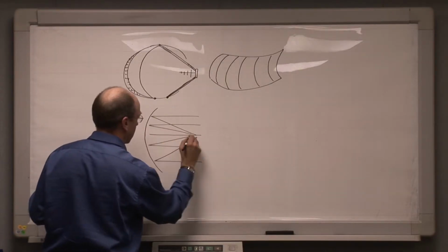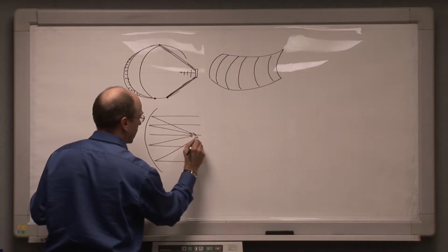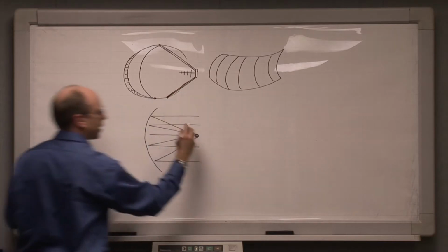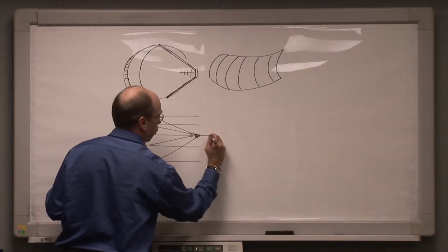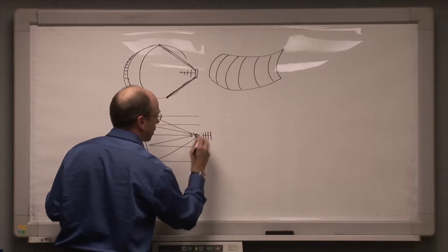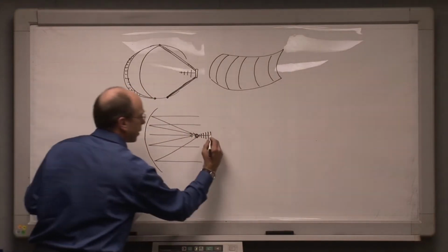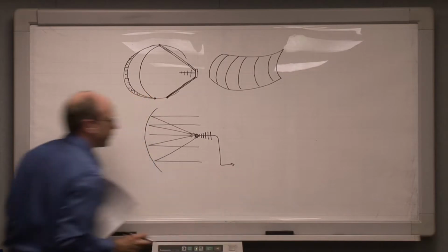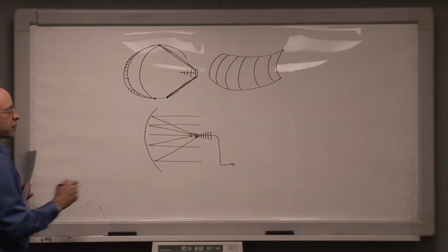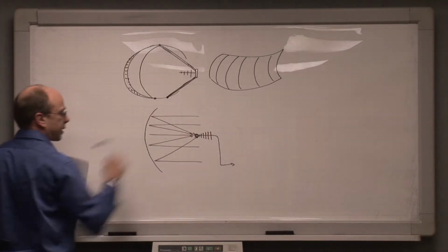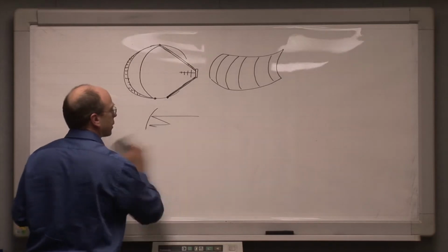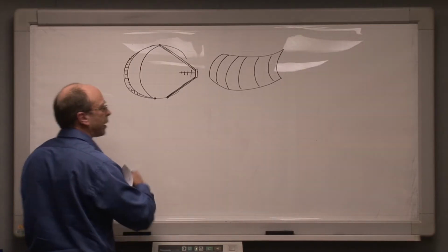a common point in space, and that point in space is where we mount an antenna, which could, if we want this to be a wideband system, for example, be a log periodic array like so, and then the energy is coupled from the dish down into a circuit of some sort. So technically this is the reflector, technically that's the antenna, but oftentimes people simply refer to these as parabolic dish antennas. Same thing for an array like this.